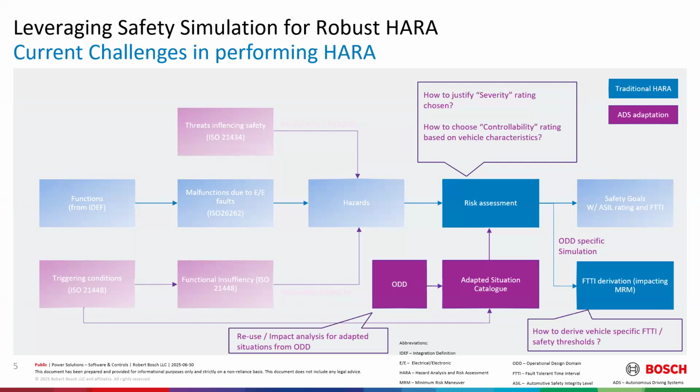The next point is the FTTA. When we design our system safety mechanism, we have to say within what time the system has to react, like within 1 second, 0.5 seconds. That decides the controller throughput, the speed, and so on. So we need a very good rough figure for our system so we can purchase the appropriate controller. We have to also maintain a balance here, right?